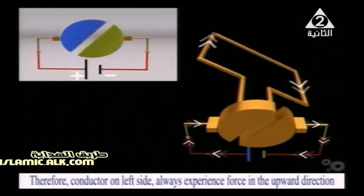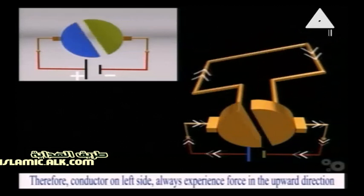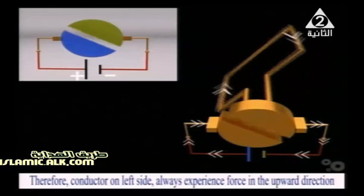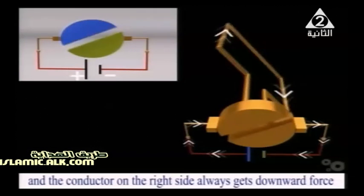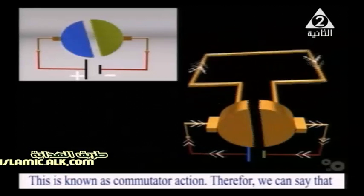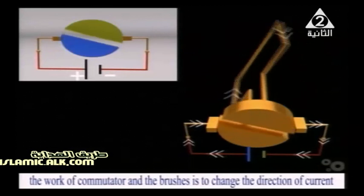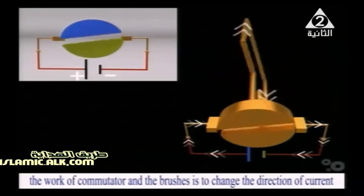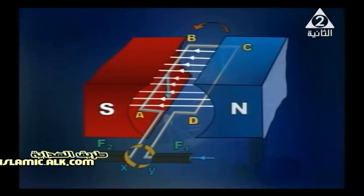When the coil just passes the vertical position, the two halves of the commutator switch over. The current, therefore, reverses in the coil, and consequently the directions of the forces on the sides of the coil are reversed. In this way, the coil will move in one direction. It is shown in front of you right now how the two halves switch over.